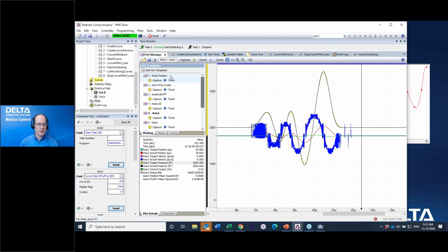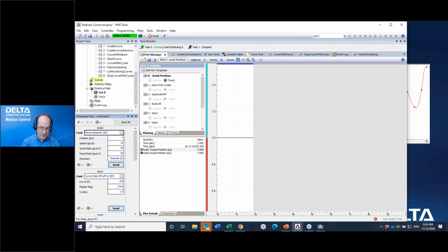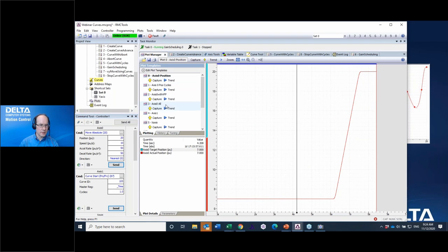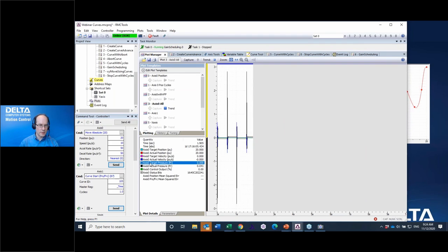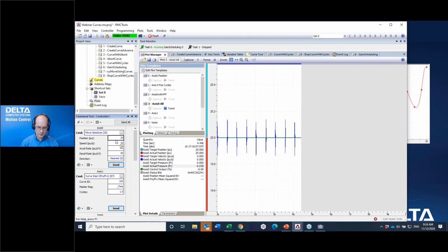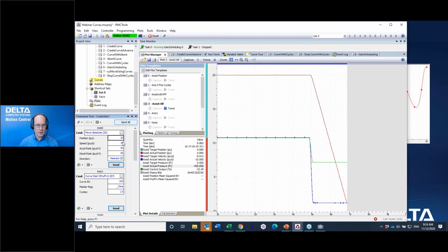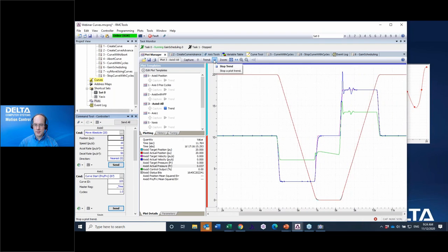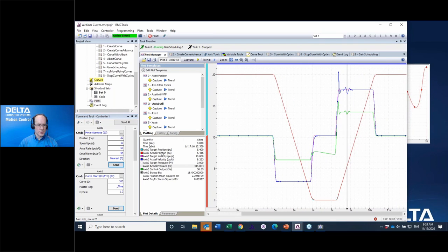So in the plots, axis 0 now, if I move axis 0 back and forth, let's see, I want to do axis 0 right there. We'll move back to 0, and then we'll move to 20, and we should see that right there, when we hit about position 5 something, we had a little wiggle in the control, and that's because we inexplicably changed the velocity feed forward right there for no good reason.